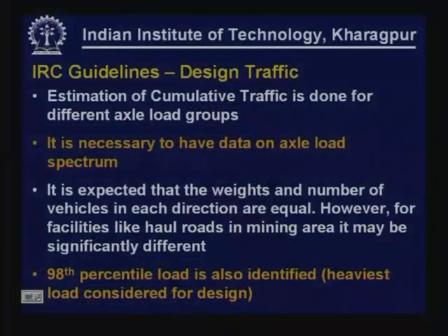So, we are not going to be talking about the 100th percentile load, we will never have any idea about the 100th percentile load, but we consider the 98th percentile load which may be exceeded about 2% of the time. So, this is the load for which we are going to check whether the pavement is going to be safe or not.